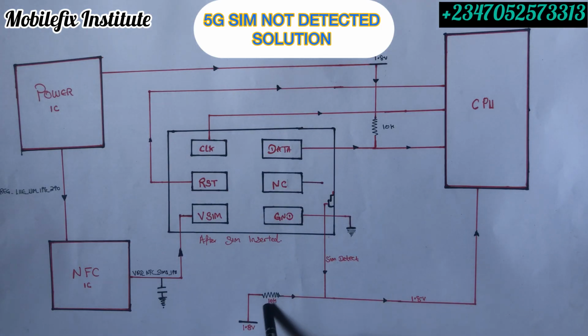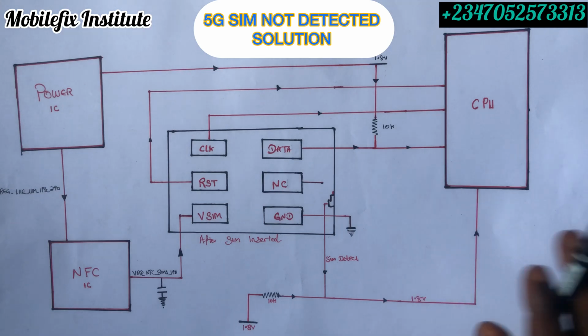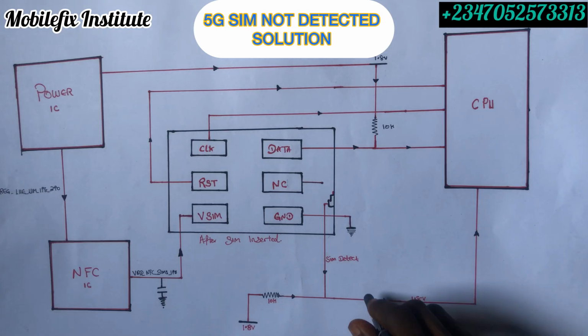Now if you turn on your phone, you test, you get 1.8 volts, then you connect your SIM card tray, you discover that you get that 1.8 volts on this side of the resistor. If you get 1.8 volts on this side of the resistor, you know that this line is working very well. I hope you understand. If you don't understand, please drop your questions in the comment box. I'm going to answer it.